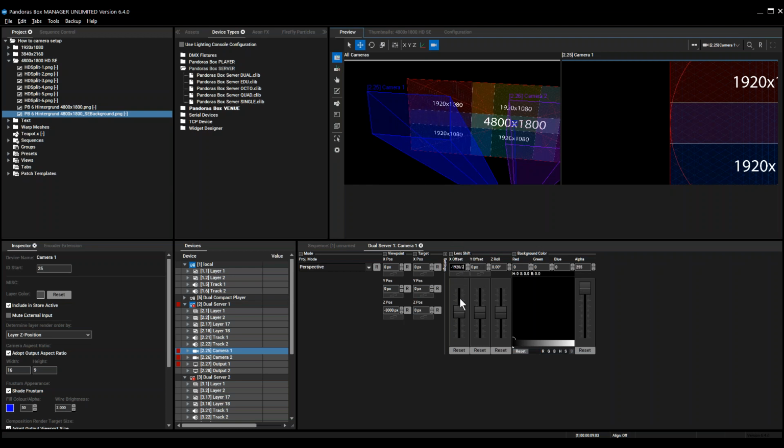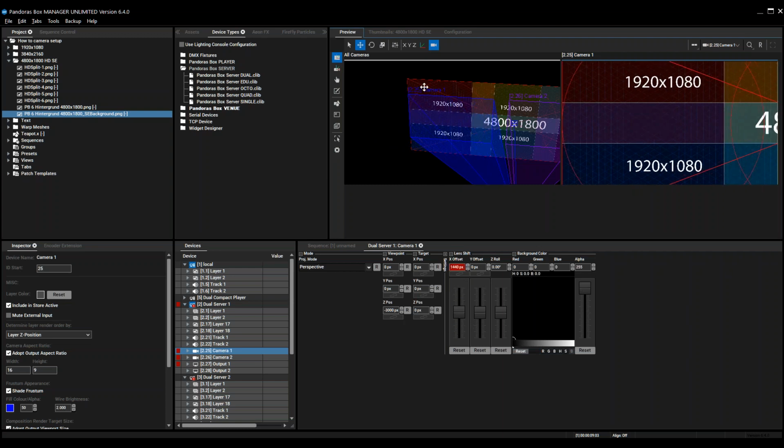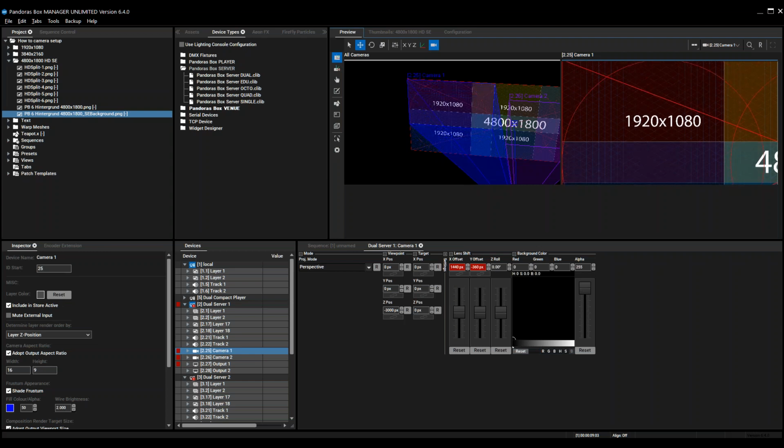So I put this calculation in here, press enter, and it directly hits the X limits exactly, right? So the same I do for the Y offset. So in this case, this is 18, or in this case, minus 1800 divided by 2 plus, what's the 1080 divided by 2. There we go. And now it's very exact on the pixel of my test pattern, right?